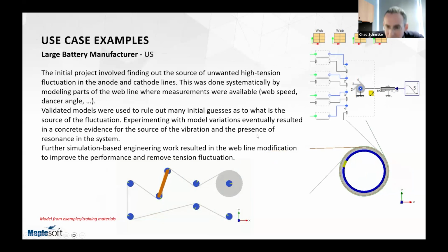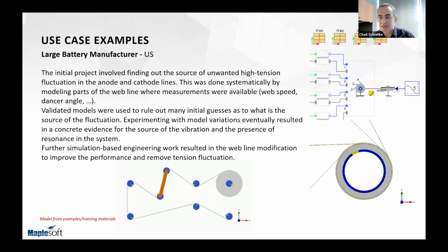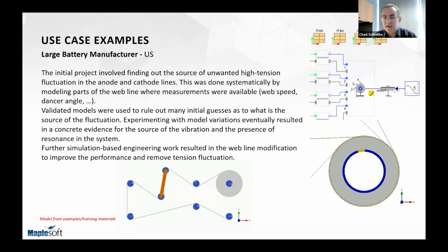This is an interesting one because of a problem a customer had been having with a given machine, and really the issue boiled down to the materials that were coming into that wind drum had different thicknesses, and these would cause abrupt changes to the radius of the wind, which meant that there would be tension changes and speed changes that would then propagate into the system. Simulation helped discover this, and then simulation provided a playground or a test bed to come up with solutions to remove those fluctuations or vibrations that they were getting as a result of these abrupt changes to the radius.